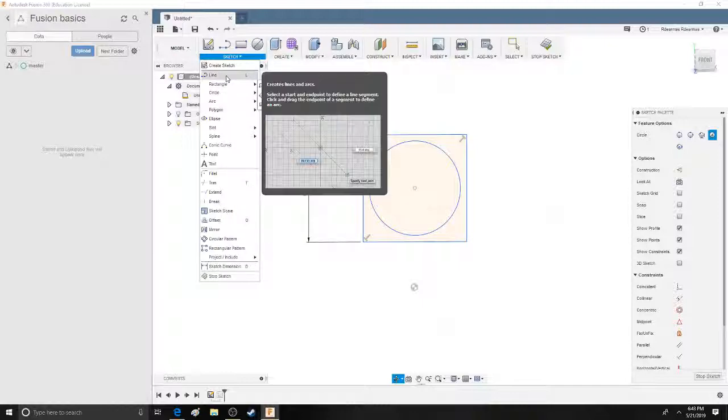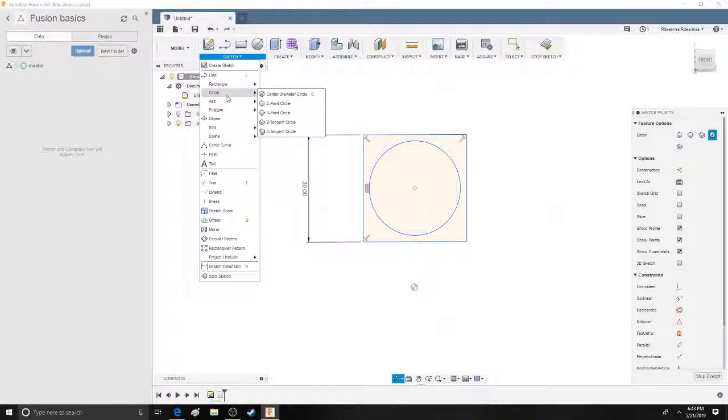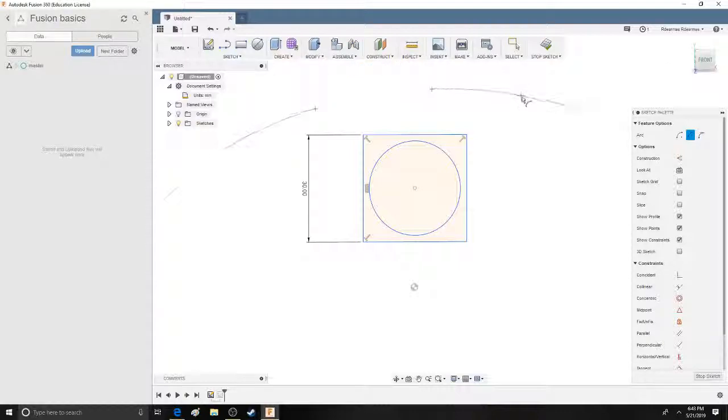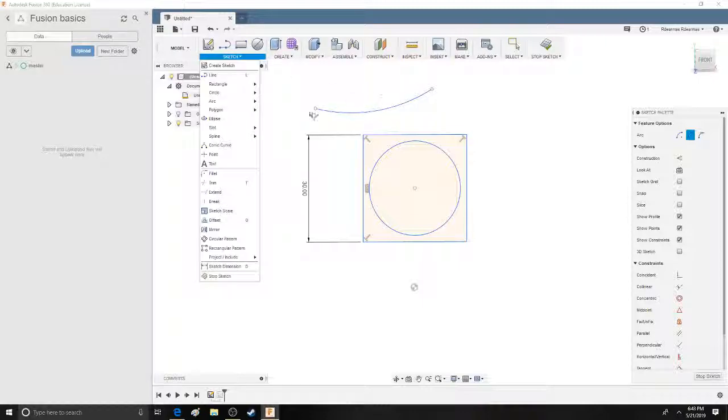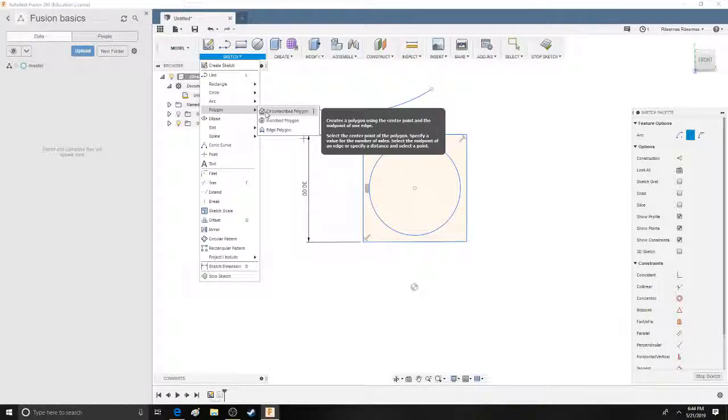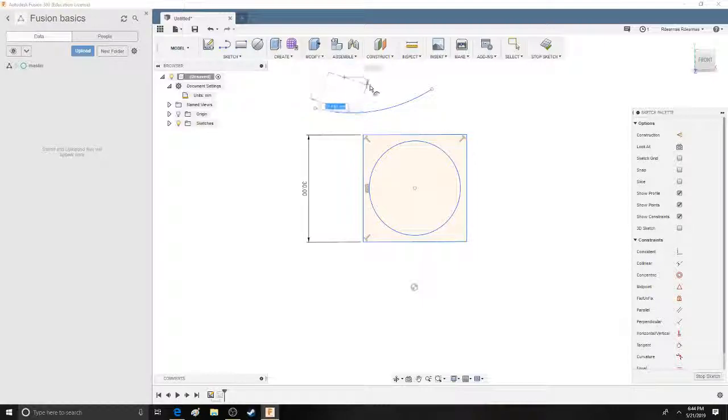And while we're down in the sketch tab, I'll go over a few more. Circle you can change to different diameters. So instead of just using circle, which you can access by pressing the C key as well, along with rectangle being R and line being L, you can use the arc tool to instantly connect points to each other. Just like the circle tool, this is another one of those multi-use tools. A polygon, like a circle, but it has the obvious 5 sides to it. An ellipse, which is a half-closed circle that you get to choose the diameter of, so you can make a circle, or you can make a very long ellipse.